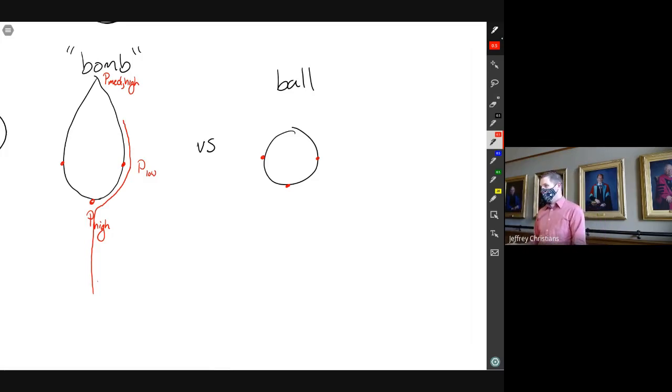And you get a long time because it's a long, slow point. The pressure change isn't super fast. So you can keep moving around the shape before you come off and form a wake. You keep moving and then eventually you get unstuck from the surface. But you have a relatively small wake because that pressure rise is slow.